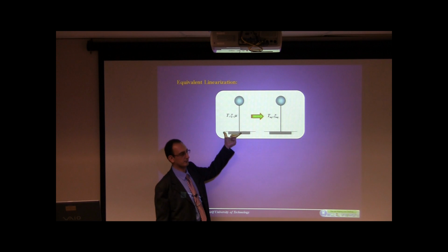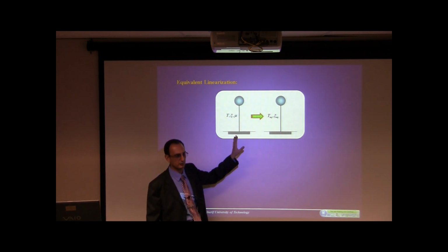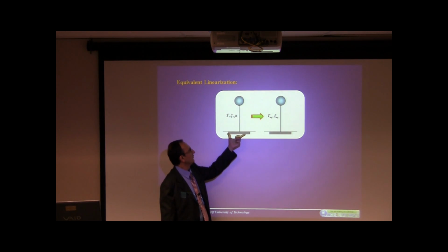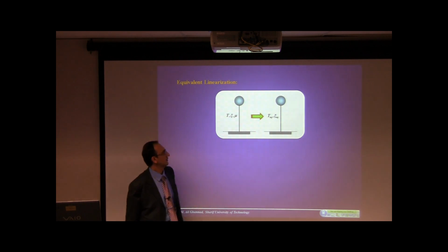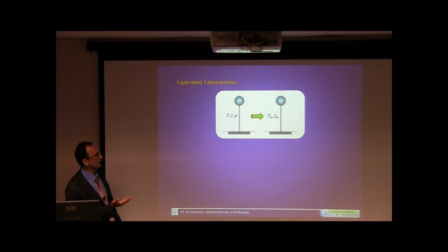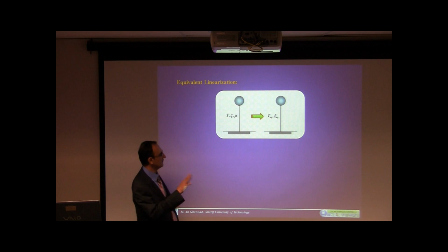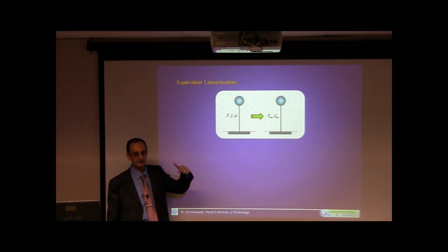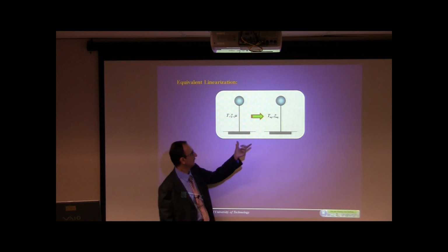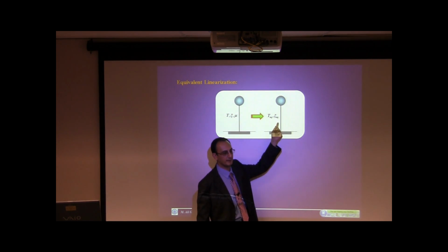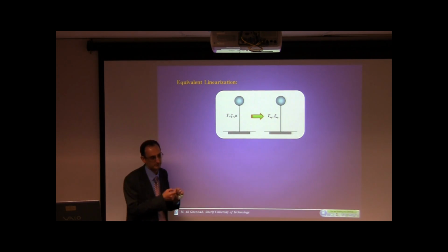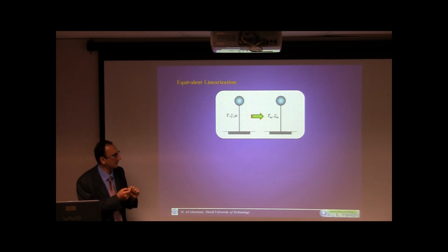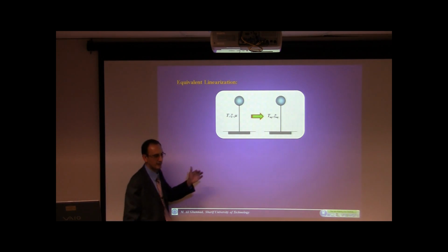I'm just talking about the fixed base structures. For a system with period T, damping psi, and a ductility demand, not capacity, ductility demand mu, we can find an equivalent system with equivalent period and equivalent damping to have the same response. Of course, it's not a unique answer, but you can find it.